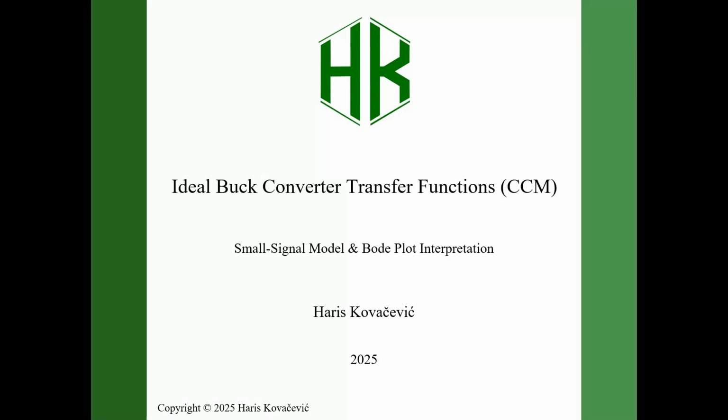In today's video, we will take a first look at the ideal buck converter transfer functions in continuous conduction mode, the small signal model that forms the foundation of every compensator design. We will explore the three fundamental transfer functions: control to output transfer function, line to output transfer function, and output impedance. We will interpret their Bode diagrams using actual hardware parameters.